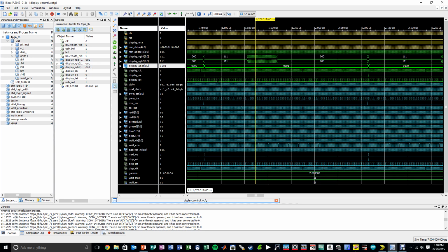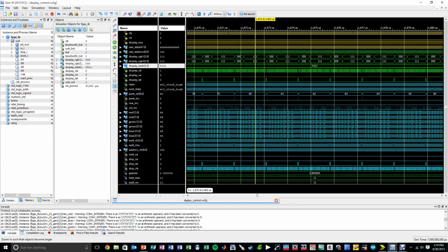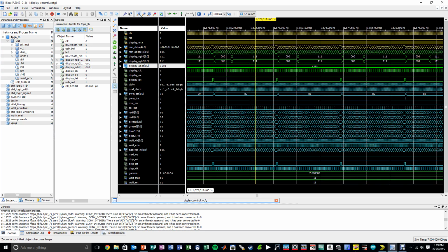Each line we write 256 times. And sometimes we write ones, which means the LED is on. Sometimes we write zeros. And the human eye will see that as different brightness of the individual LEDs as you get a full frame eventually. Exactly. So if we zoom in even further, now we start to see the display clock and the display latch start to appear.